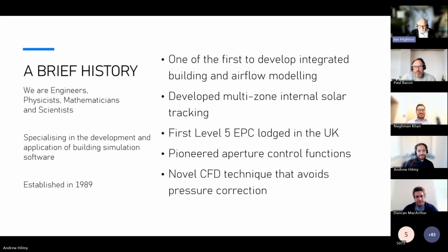Yeah. And since then, we've seen various other regulatory changes, but the big differences in terms of what the software is now capable of and the developments that have been made are very much more about lighting, daylighting in particular. So can you harvest daylight? Can you reduce the amount of electrical lighting gain, artificial lighting gain effectively? And then you've got other metrics now like CBDM, climate-based daylight modeling, which again is a much better way of actually appreciating how window design, window placement, etc., blind controls can give you that sort of optimal performance